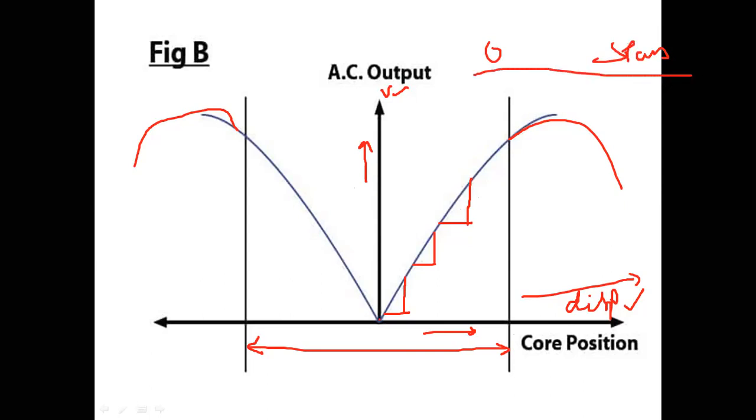So if zero and span calibration cannot be done, then the error will not be a constant value. It will be a dynamic error, and it will show wrong values every time. Okay, means the repeatability and reproducibility will be very, very less. Okay, so this is about the characteristics of the graph.